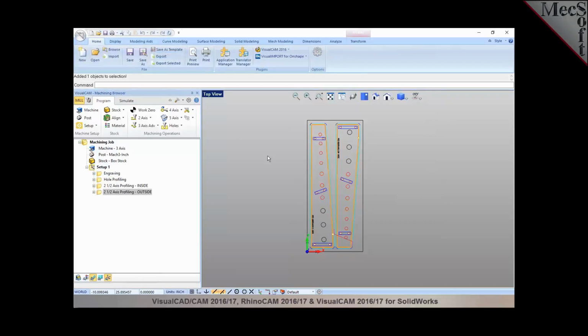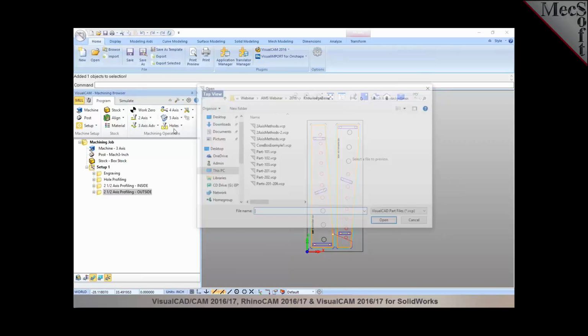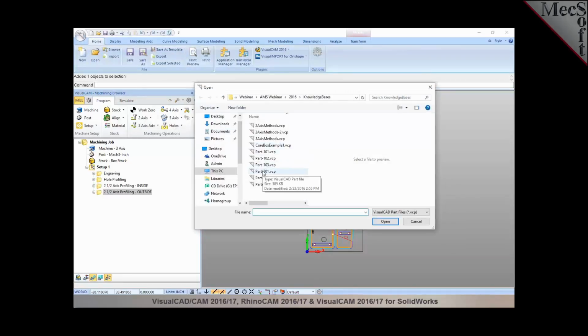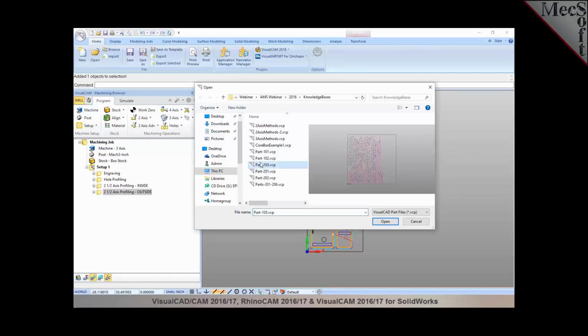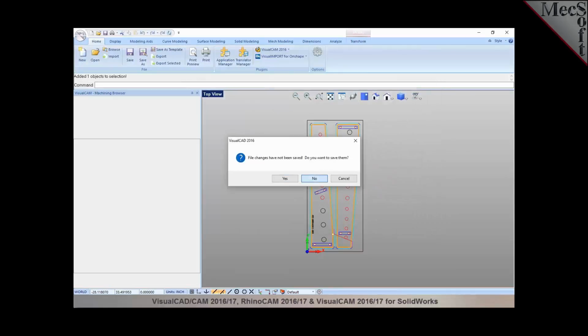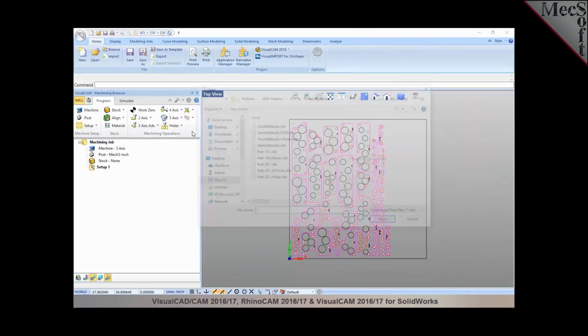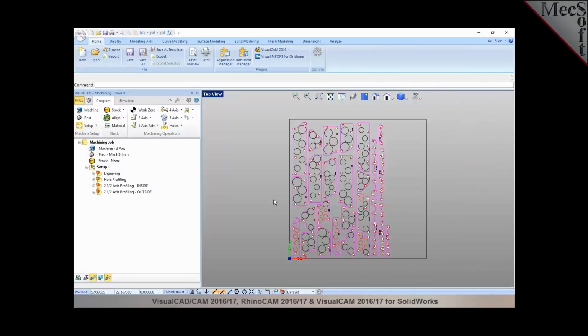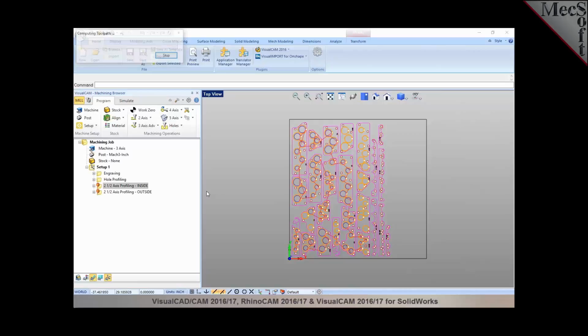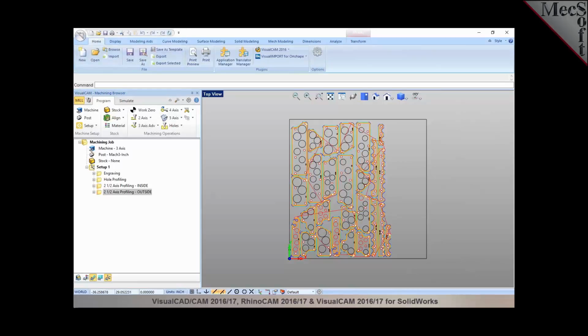So here's an example of how you can program effectively on geometries that require 2-axis machining, since these rules are being set to geometries like curve geometries or sketch geometries that are in your file. You can click on load knowledge base, and then pick the knowledge base where you have the rules set, and you'll notice that it automatically pre-selects the geometries for your machining process. This is a very powerful feature, makes your workflow a lot easier and more productive, so you can have several parts programmed in a very short span of time.